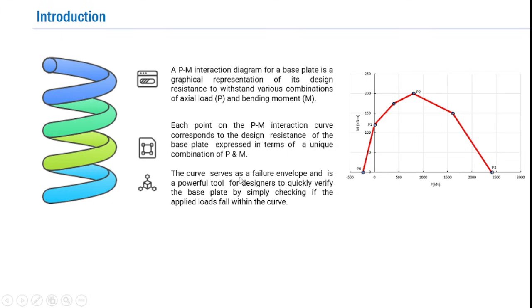Thus we conclude that the curve serves as a failure envelope and is a powerful tool for designers to quickly verify the base plate by simply checking if the applied loads fall within the curve.